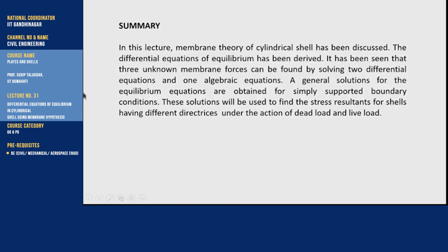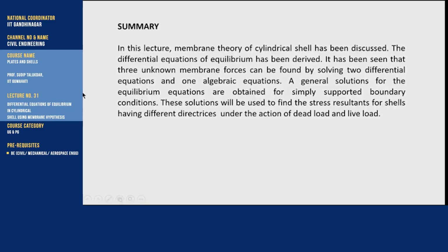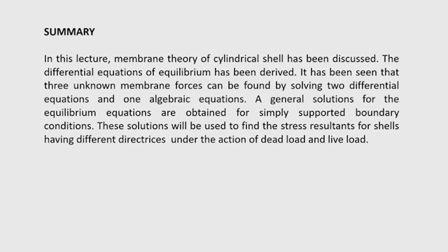So, today we have completed the derivation of the differential equations of equilibrium of a cylindrical shell using the membrane hypothesis. It has been seen that 3 unknown membrane forces exist in the differential equations, and there are 3 differential equations also. So, this problem is a statically determinate problem, and we have attempted a general solution of the equilibrium equations for the simply supported boundary condition.